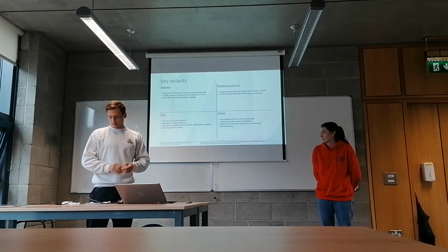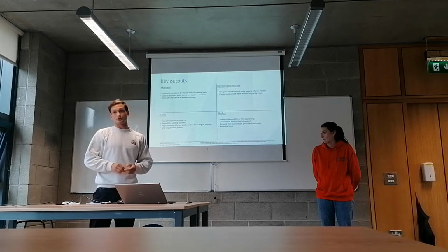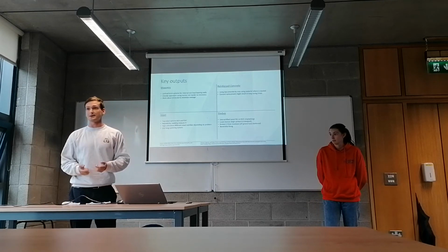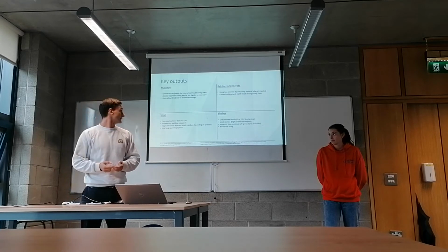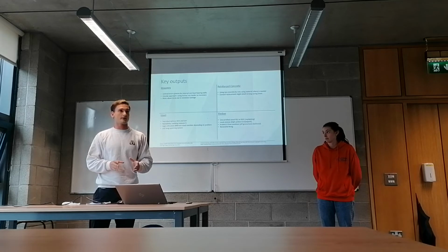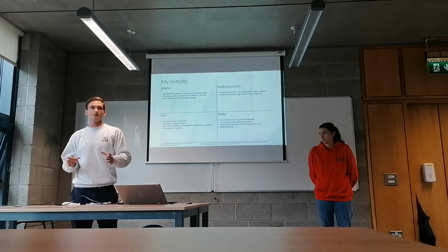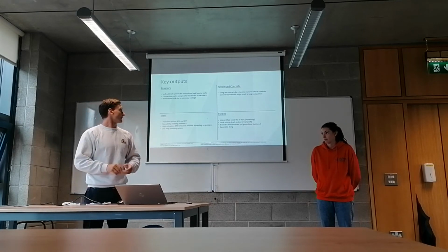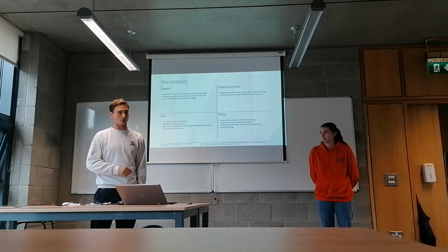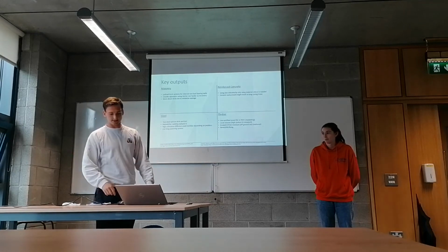And yeah, for timber, you should use certified wood, which gets replanted, and you want to use local sources because transport makes up most of the carbon emission for timber. Yeah, there's way more hints in the article, but we won't go through all of them. Yeah, and that's it.